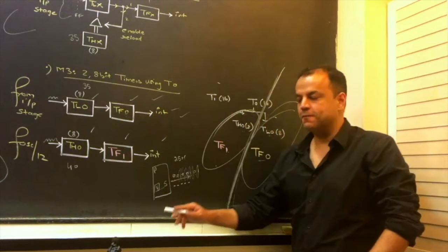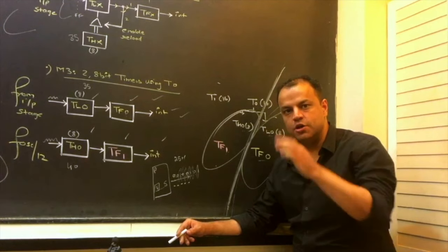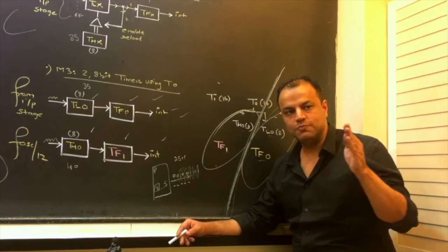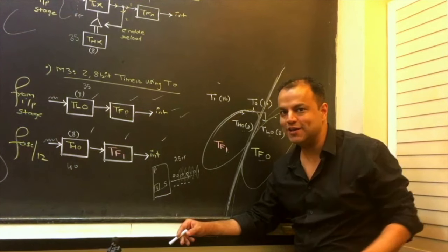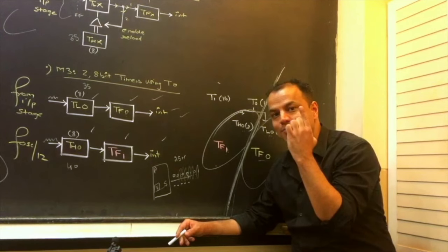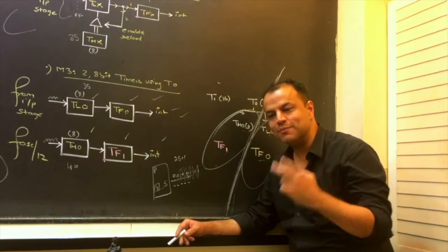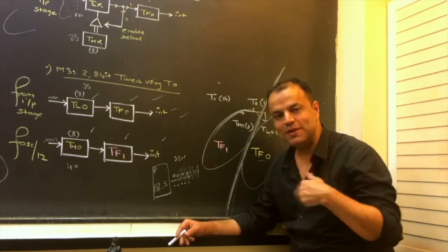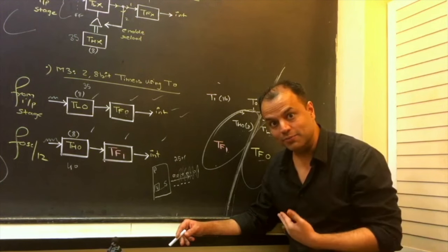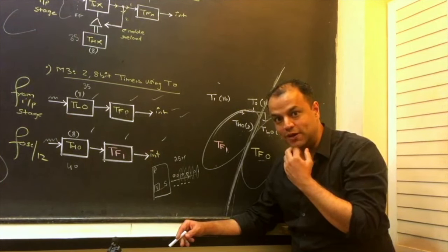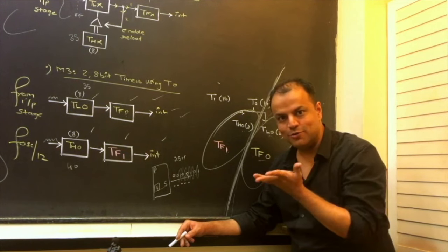That means whenever you do serial communication, timer 1 is lost because it is engaged in doing serial communication. That means you have only one timer now, timer 0. All this while you were telling the whole world, I have two timers. Whoever wants two delays, come to me, I will produce it. Now suppose somebody comes and says, we've heard you can produce two delays together. You have only one timer, you don't want to be red-faced.